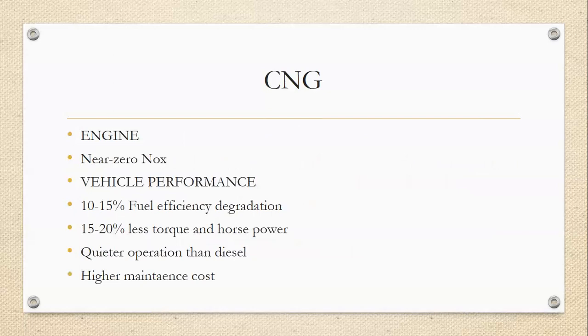The engine which is fueled with CNG fuel will have very near zero NOx emissions. And about vehicle performance, there is 10 to 15 percentage fuel efficiency degradation, 15 to 20 percentage less torque and horsepower, and quieter operation than diesel.